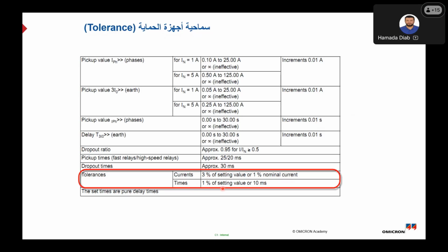The tolerance definitions in relative and absolute matter if you are using a general test module, such as quick CMC, ramping, pulse ramping, test sequencer, and so on. Because in the general test module, you have to define the assessment or the tolerance level of the protection testing. Okay. On the other hand, if you are working with a protection testing template or protection testing library, you will find these values ready-made for you, inserted inside the test object files, and you don't have to worry or enter them manually. I'm just explaining to you, if you are starting from scratch and using the general test modules, you have to differentiate between the relative and the absolute test values.